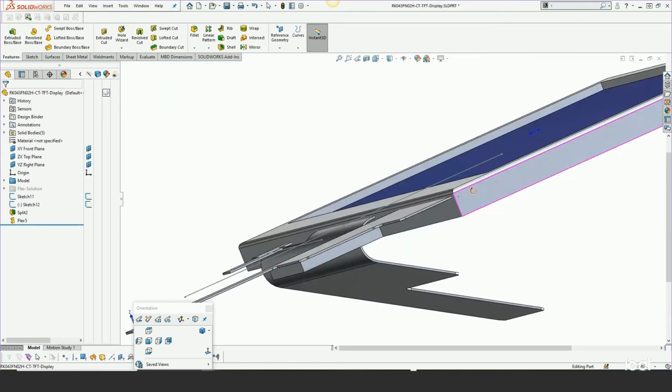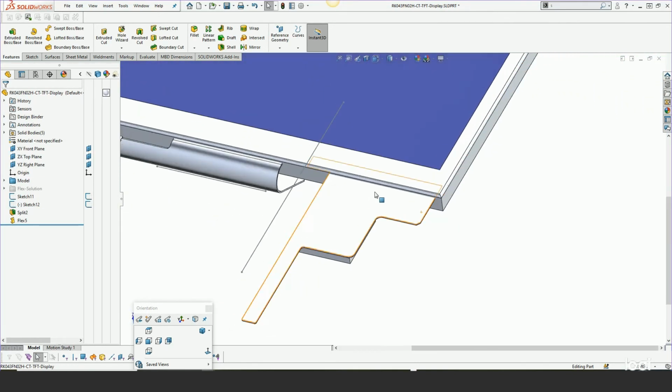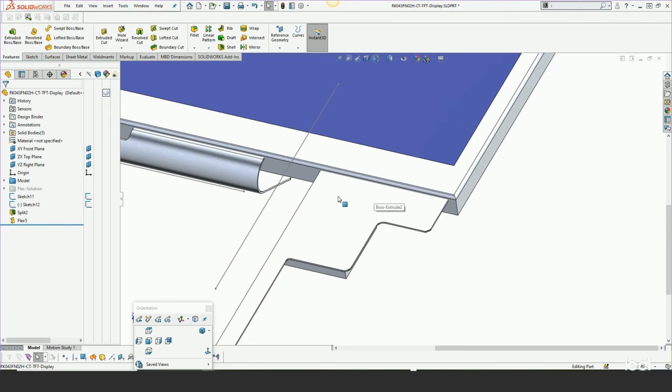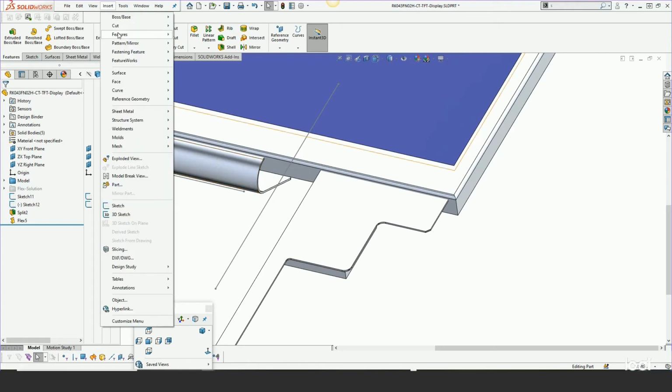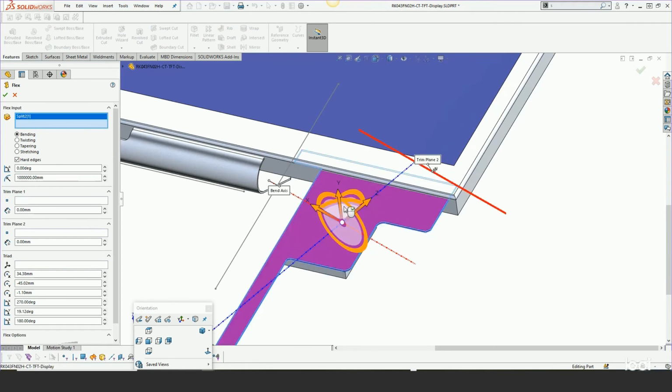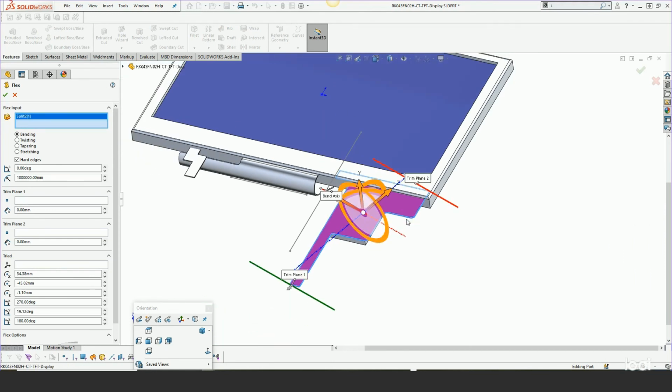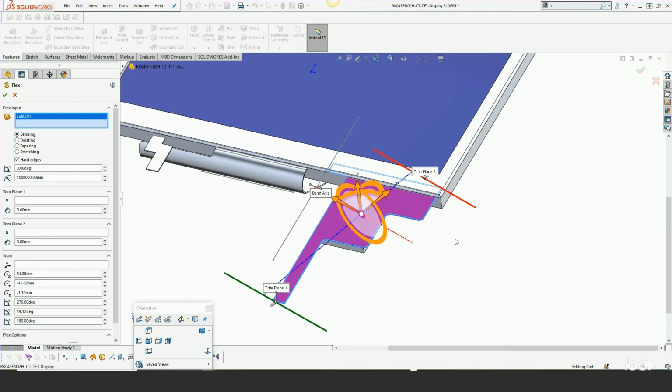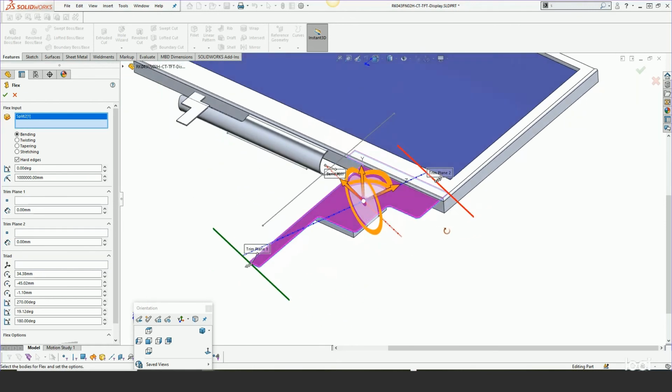So there's our bend. Now I can go and apply a bend again to this one and make it different from my first bend. So I'm going to apply my flex feature. And again, you can see the bounding box is not very smart. It kind of finds the extent of the bounding box, but doesn't mean it's going to be necessarily oriented correctly or the way that we would have predicted it.